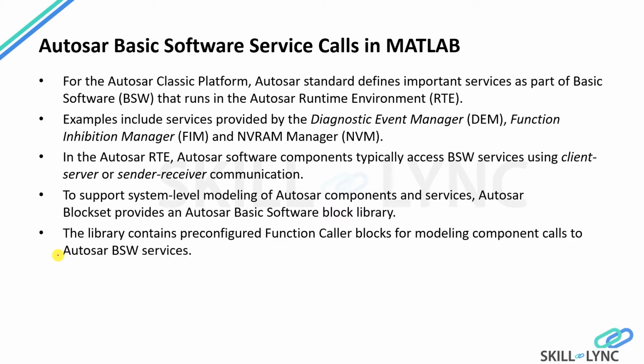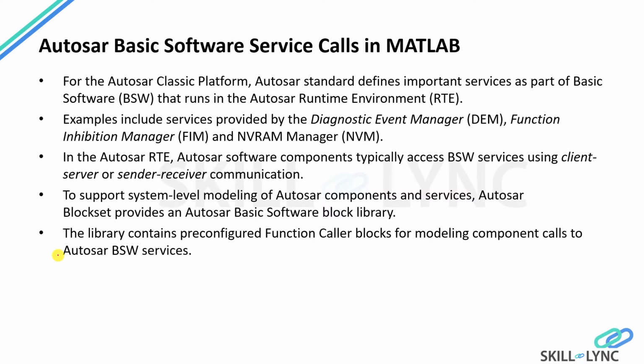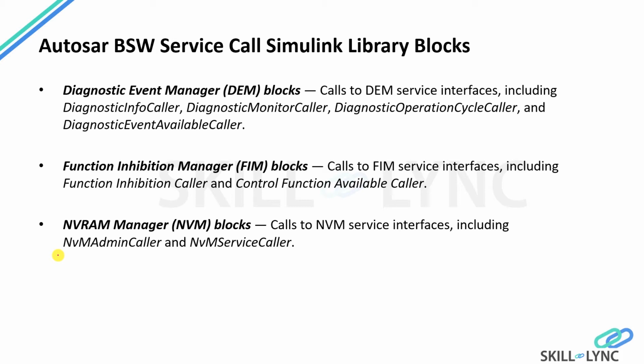To support system level modeling of Autosar components and services, the Autosar blockset provides an Autosar basic software library, and these basic software libraries have some pre-configured function callers which are useful for modeling of the Autosar BSW services.